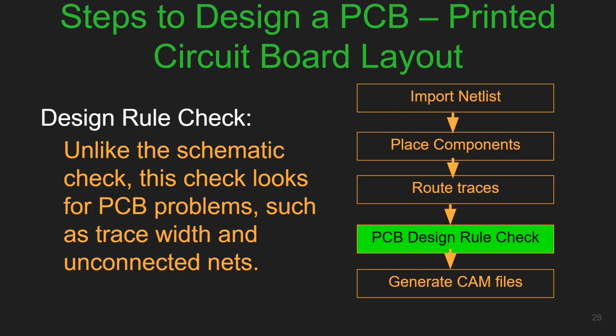It also involves layout versus schematic check, electrical rule check, and if you have any antennas in the design, then checking of that. It is particularly recommended that a batch mode design rule check always be performed prior to generating the CAM files.